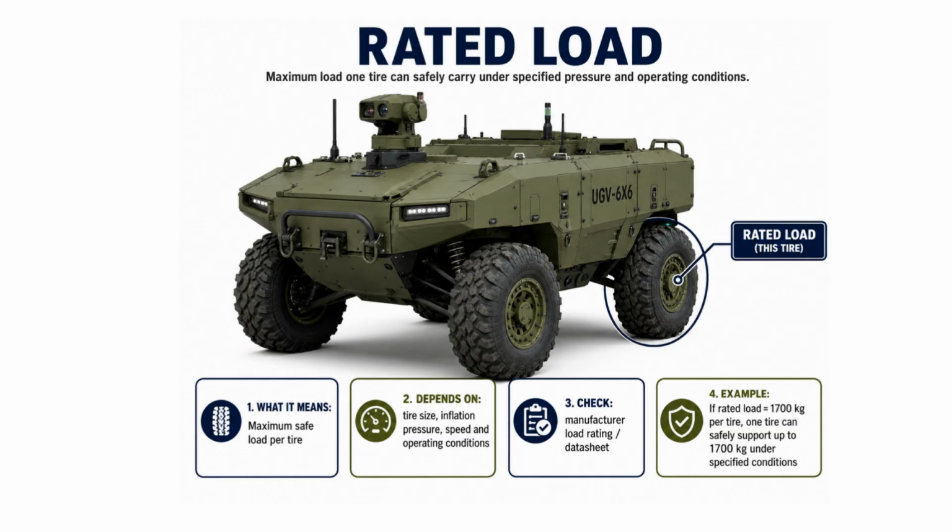Rated load should not be confused with a normal static load acting on the tyre. The engineer must first calculate the required capacity by considering static load, dynamic forces, and an operating margin. The selected tyre's rated load must then be equal to or greater than this requirement.